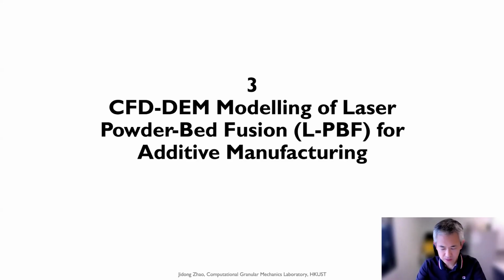So let's continue with our lecture. We have introduced the coupled CFD-DEM for simulation of debris flow. Typically, we use unresolved CFD-DEM for that purpose. Then we introduced different coupling schemes, like semi-resolved and fully resolved, and we typically use a hybrid of resolved, semi-resolved, and unresolved together for more practical prediction.